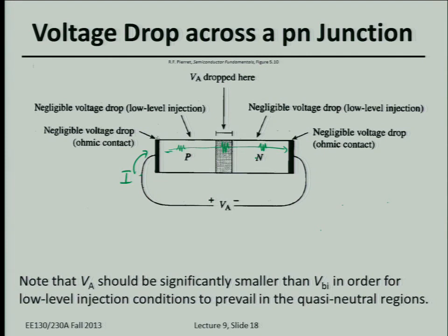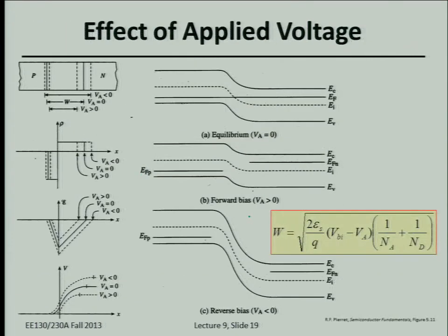Okay, and one thing in the past, so the applied bias, so that built-in potential, okay, let's see, let's go here. So at equilibrium, you can tell it's at equilibrium because the energy band diagram shows the Fermi level is constant. But as you apply a voltage, the Fermi levels will split, and it doesn't matter if it's positive or negative bias.